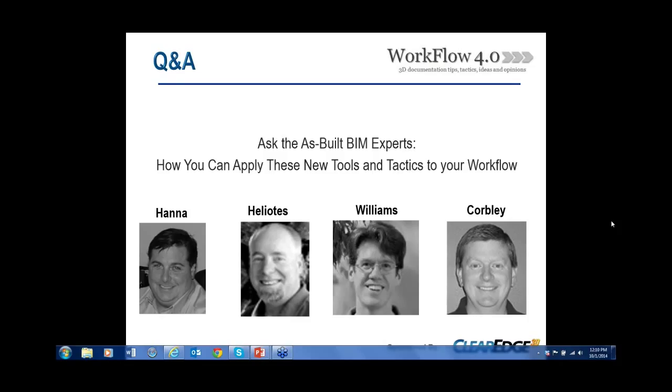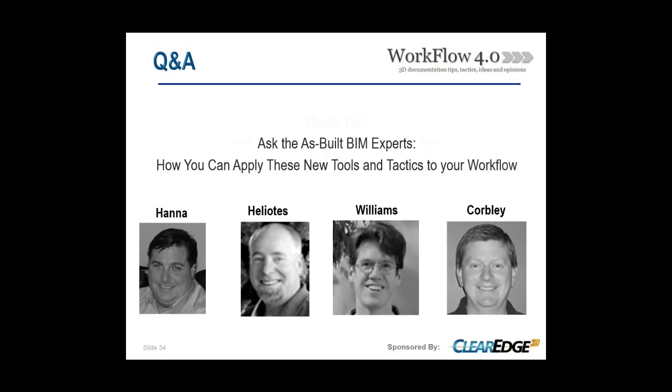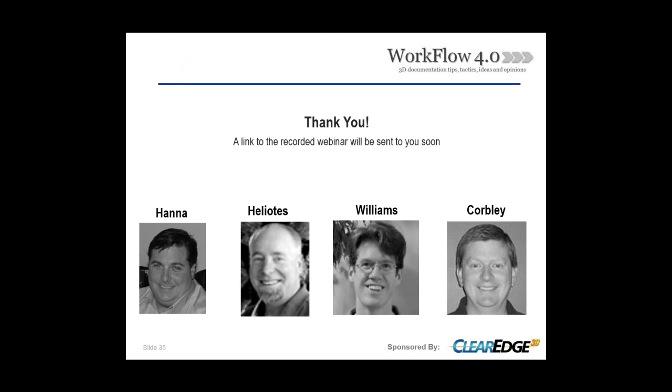Okay. And we've got time for just one last question. Looks like it's going to go to you also, Kevin. What duct type, transition type, elbow type does Edgewise bring into Revit? Can this be defined by the user? It brings in, and I'm reading off of what Revit is calling it, a rectangular transition length standard. And from there you can change it to whatever else.